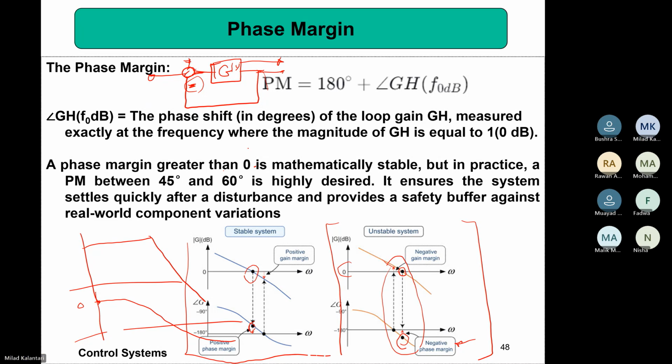What will happen? Yes, because this G of j omega induces a 180-degree phase shift by itself. And in closing the loop, you have another negative sign always initially, right? And these two become a positive at the end. In fact, for that special frequency, this loop becomes a positive feedback. When you have a positive feedback at a certain frequency, then it may have a chance to oscillate at that frequency.